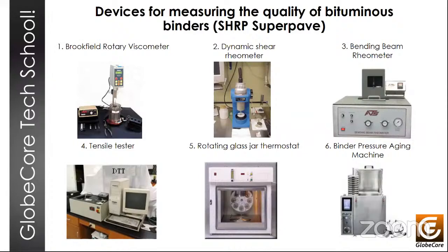So the features of quality assessment in accordance with European standards are as follows. Simplicity, relatively low costs, good reliability, and repeatability. So the main disadvantages, however, are the use of basic conditional quality indicators, such as penetration and softening point, which indirectly characterize the performance of the binder in asphalt concrete, and the limited ability to predict the service life of road surfaces using these parameters.